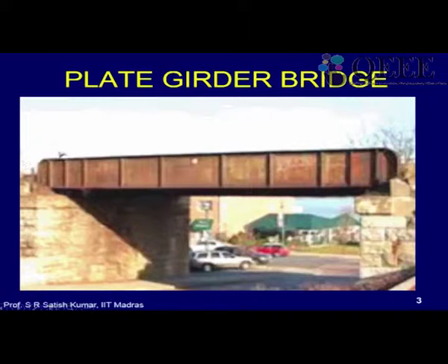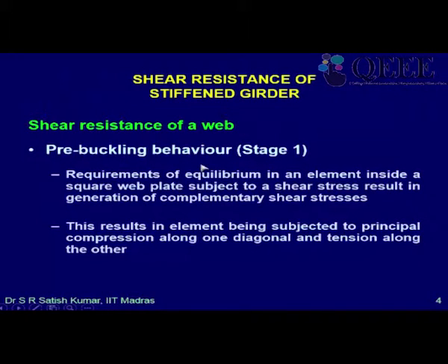So that depends. Now, if you have a wheel load like a vehicle moving, and the vehicle is in the center, whatever shear it produces has to go to the end, right? So shear will be constant from here to here. So we may want to keep the spacing equal. Okay, so that also is a possibility. Now the first question is why and how the web will buckle in shear. Okay, so what really happens?